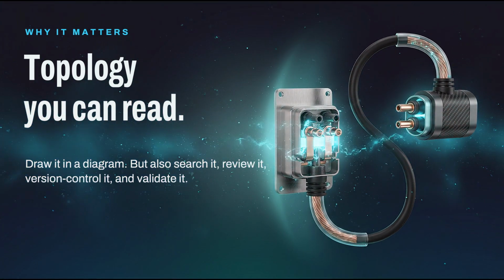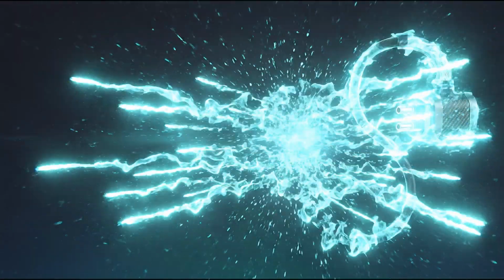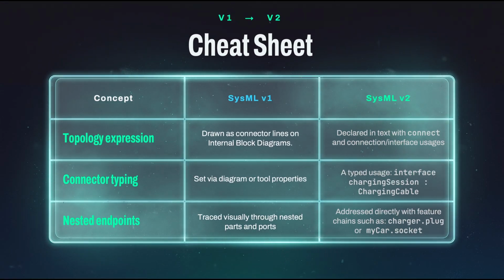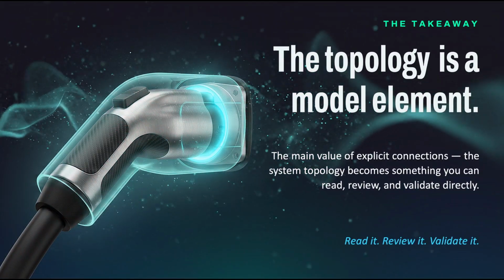The architecture can be drawn in a diagram, but it can also be read, searched, version controlled, and validated in text. Before we wrap up, here's the V1 to V2 shift in compact form. In V1, the diagram often carried much of the topology story. In V2, the topology can be part of the textual model itself. Connector typing also becomes explicit. Instead of depending on a dialog box or a diagram property, the model text can state exactly which definition types the connection. When endpoints are nested, dot notation or feature chains give us a clean path to the port we want to connect. That is the main value of explicit connections in SysML v2.